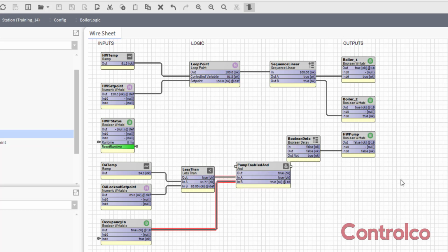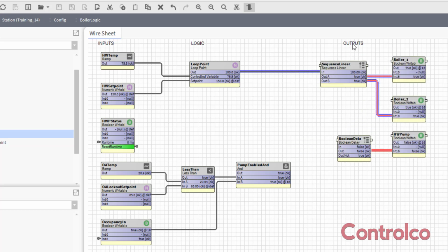And then I'm going to make some more room here on my wire sheet because it appears as though I'm running out of room. You may have noticed at this point that I renamed this block, but I haven't been renaming these other blocks. I'm renaming this one because it's the result of some other logic combined. And if I come back to my wire sheet in 6 months and I want to have an idea of what I was going for when I originally created the wire sheet, renaming some of these blocks gives me clues as to where my mind was when I created the original logic.